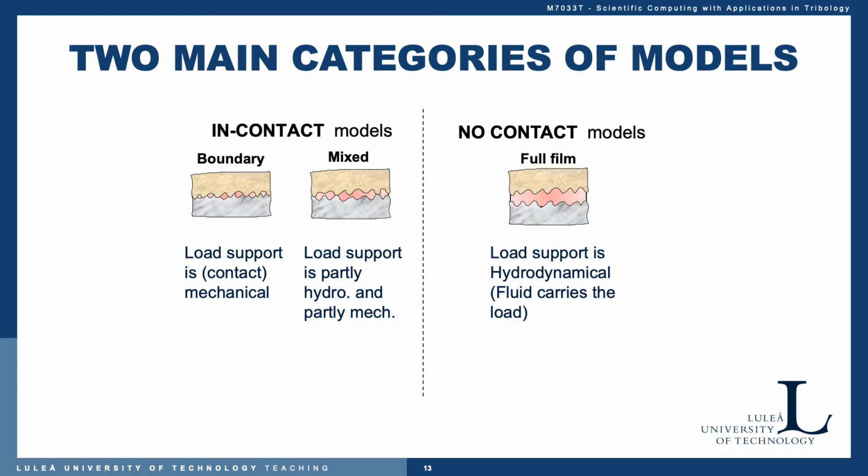And then going further into the boundary, closer and closer to more and more real direct contact, the load is supported directly by the asperities, and the fluid has negligible influence here on load support. It can still provide very vital things to the contact, namely the additives in the fluid, which hopefully can generate tribofilms that protect the surfaces from wear.